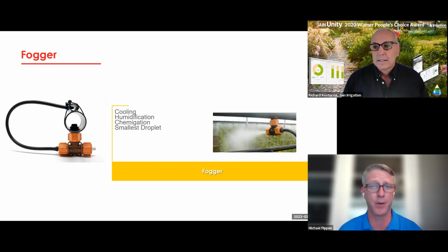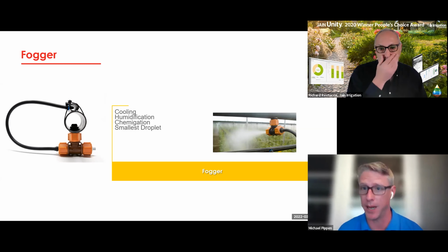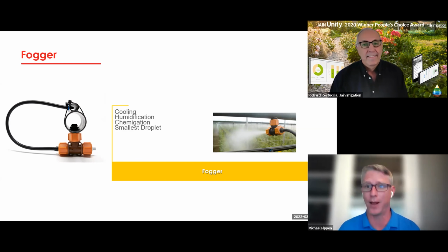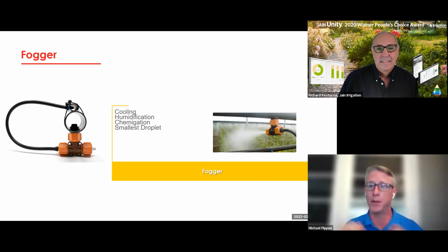We're also going to have airflow through these, especially indoors. Outside, you're going to have plenty of airflow. Those things are going to evaporate pretty well, and we're going to have a little bit more flexibility. If things get wet, they'll tend to dry off a lot better, like they would in the Pacific Northwest in the summertime, right? Lots of evaporation, not a whole lot of challenge getting those leaves dried off. But even in that place, we really don't want the water touching the fruit in that cooling application. So the goal is to have a very minimal amount of water in either cooling or humidification, very little water actually landing on the plant itself.